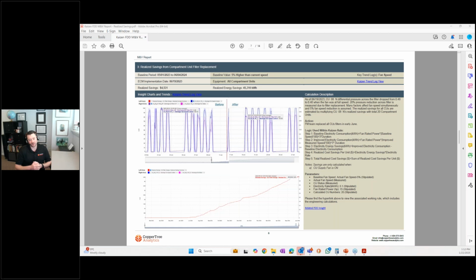And that helps us a lot with the new commissioning in particular, or the retro-commissioning approach, where we're trying to validate whether what was designed on paper actually got implemented properly. The interesting thing about those faults is that they don't surface very often, right? That's not something you can often catch easily in commissioning, because the conditions aren't there. You might be commissioning in summer and it's a winter heating fault that you're going to catch, having to do with boiler staging or hot water pump sequencing or something. So we can simulate those conditions in the off season or on demand. So that hopefully answers that question.